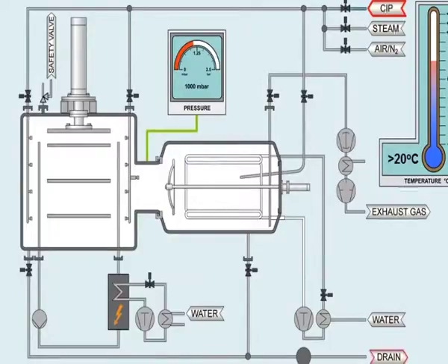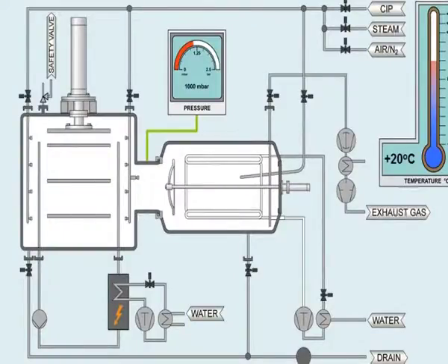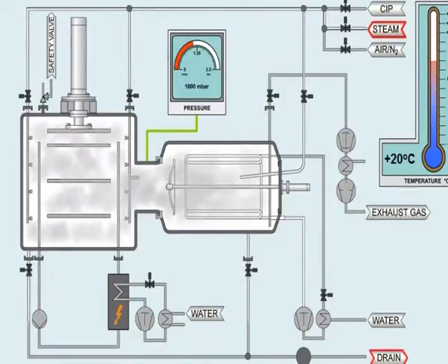Heat is supplied, which is transferred as latent heat, and ice sublimates directly into the vapor state. So the main principle of the freeze drying method is conversion of ice directly into vapor without conversion into the liquid phase. The primary drying stage removes easily removable water, about 98 to 99%. Now come to the next step, secondary drying. The main water is removed in the primary drying process. A very small quantity of remaining water is removed in the secondary drying process.